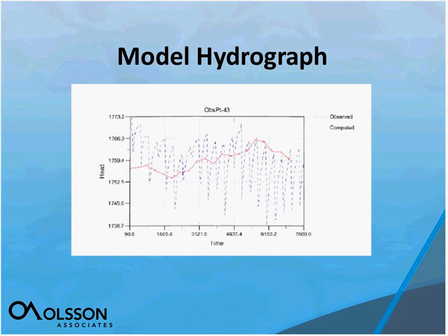And the blue dashed lines are the model's interpretation of the water levels over that period. As you can see, the process of groundwater modeling incorporates a period of calibration, where you're calibrating your model to make sure it is consistent with the reality of the measurements taken. And the one I'm showing you here does have fairly good consistency, with the high water level measurements corresponding with the high water table computed values in the model.